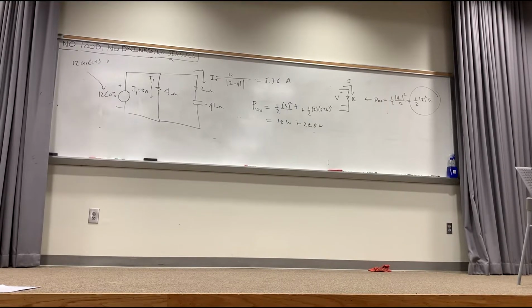The average power dissipated by an inductor or capacitor is 0. Everybody understand that? Now really, what's going on with inductors and capacitors? They're energy storage devices. What you basically get is a magnetic field created around an inductor that has energy in it, and then the energy is dumped back into the circuit. It's sloshing back and forth. Same with a capacitor. A capacitor stores electrostatic energy, then dumps it back in the circuit. A resistor burns it up. So a resistor literally is something that dissipates heat. That's the thing we really think about.